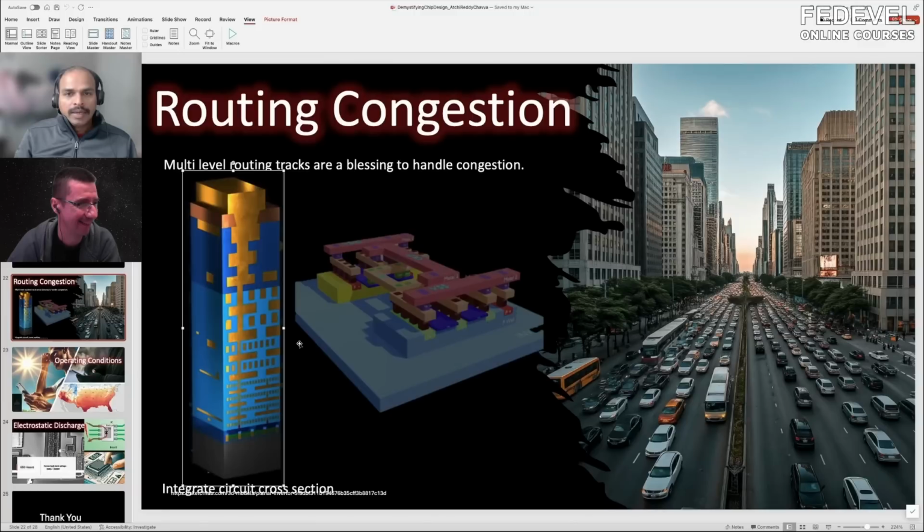Wow. So you see this here on the bottom side where I'm pointing my cursor. This is the base where we have the active devices like transistors. And then immediately on top of that, what we call the first layer of routing. And then you have the second layer. These alternate layers run in orthogonal directions. If the first level is running horizontal, the level above will run vertical, like in Manhattan directions. And the next level above is again horizontal, vertical, horizontal, vertical.